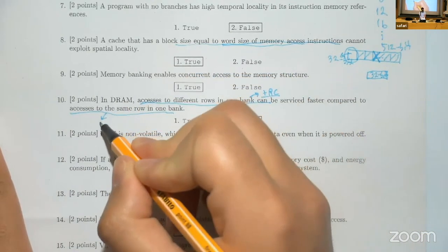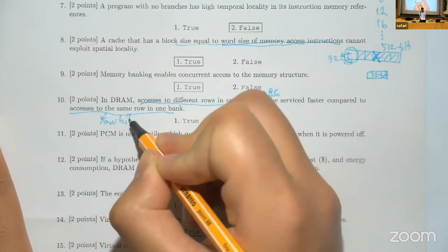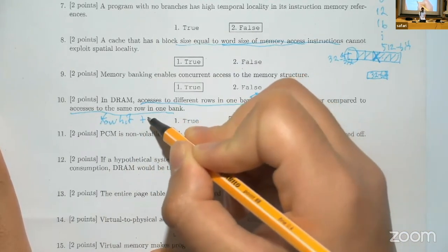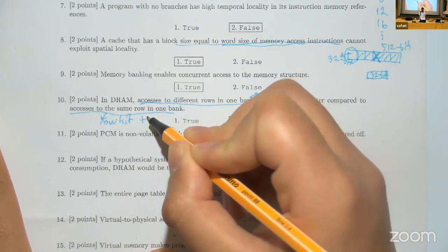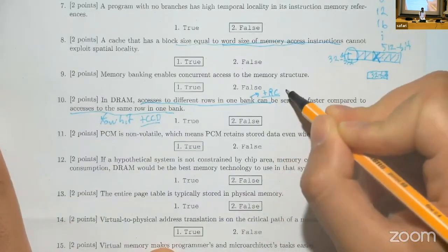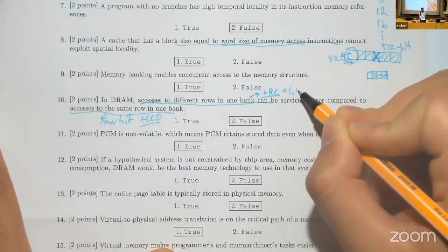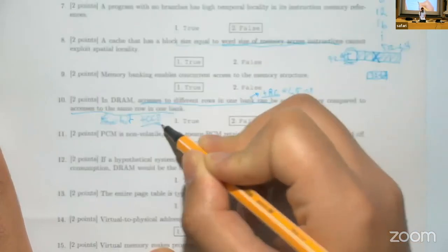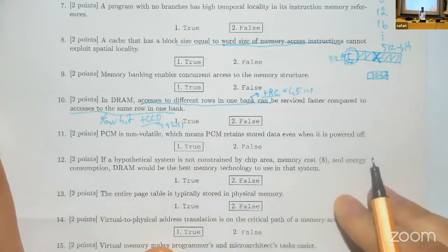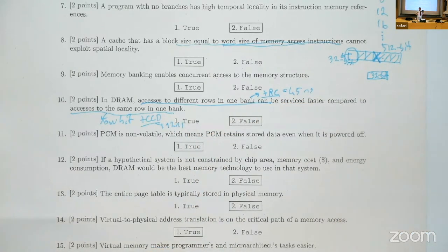This is a row hit. And then the memory controller only has to wait for a much smaller latency. This is like tCCD, versus tRC. You can think of tRC as in the order of 45 nanoseconds, while tCCD is much smaller, like, I don't know, smaller than 2 nanoseconds. Basically, we're questioning row conflict and row hit latencies here.